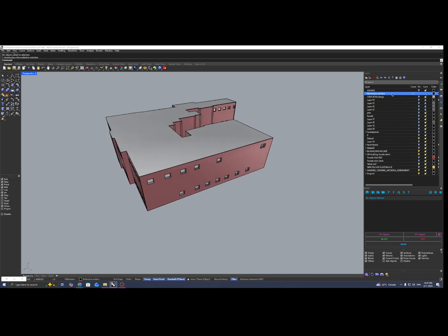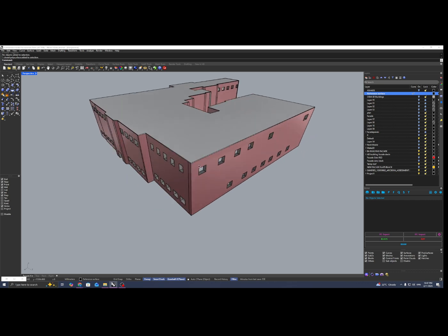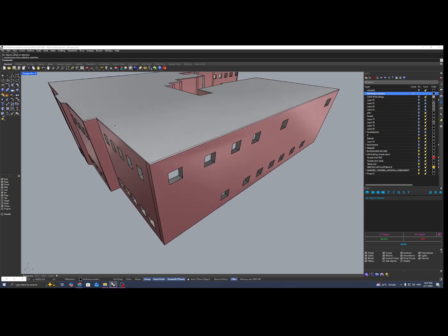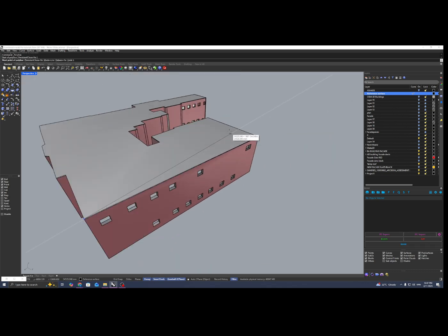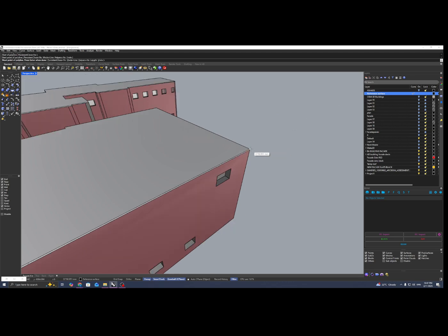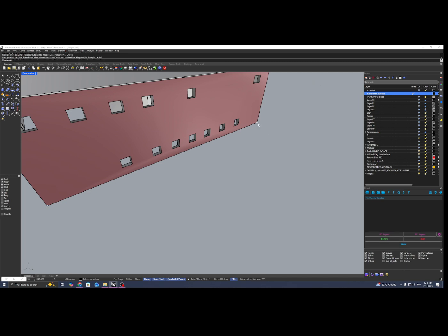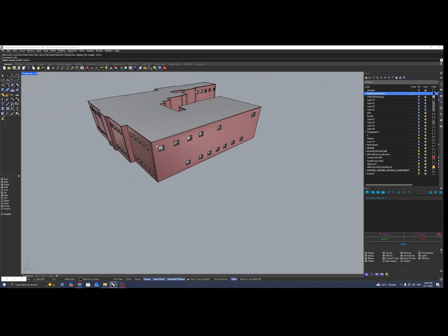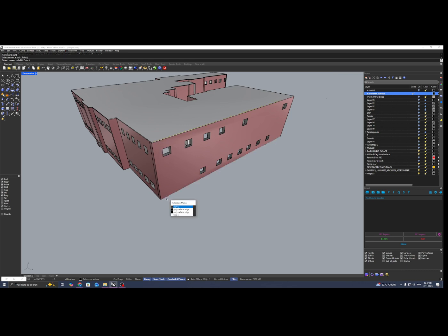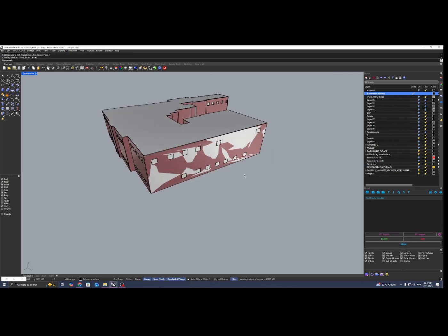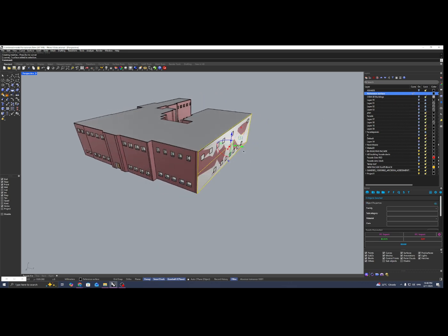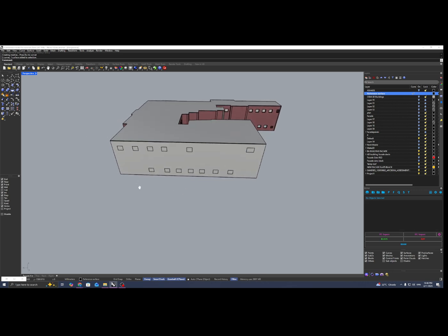To do that, I've just got a layer called reference surface to reference in some geometry that we'll need in Grasshopper. So to start, I'll simply draw a line connecting one end of the top to the other, and the same at the bottom. Then I'll just simply loft them. Cool. And then I'll just select all the objects on that layer and move it out by about 1 mil just to stop that clashing from happening.